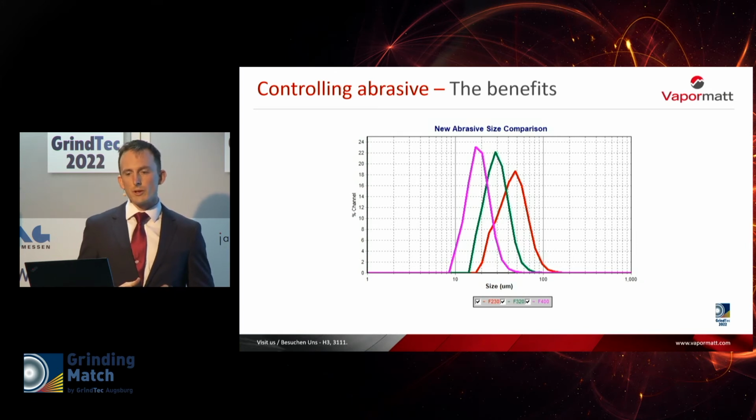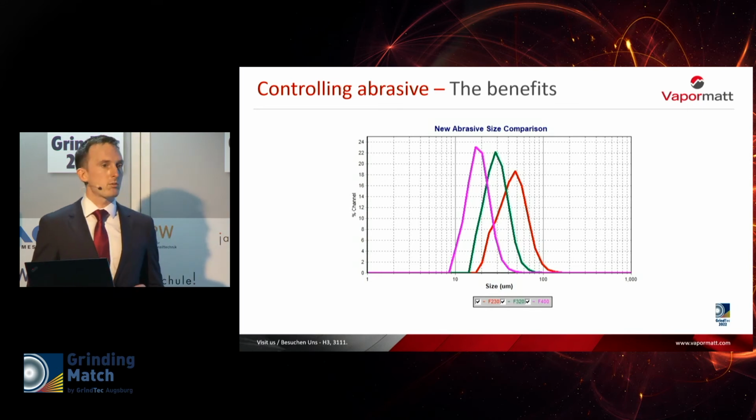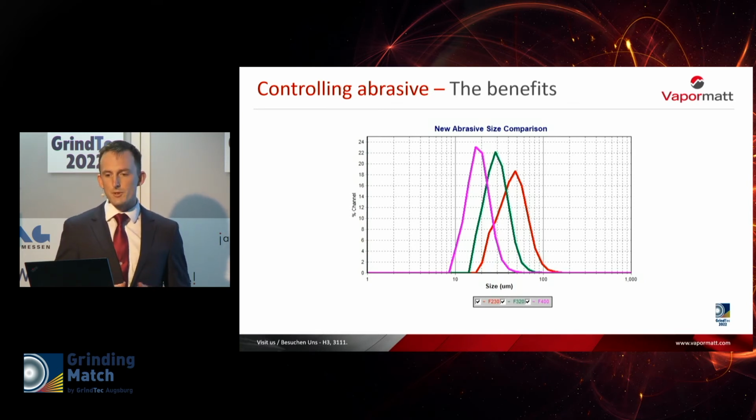For the purpose of tooling manufacturers, this is normally going to be a white or pink aluminium corundum, and I've shown three common sizes that are used by them when they are talking about wet blasting. With a well-managed wet blast process with the correct abrasive, the tolerances on edge honing can be plus or minus 5 microns for inserts, and plus or minus 2 microns when we are talking about solid tools, drills, mills, taps.